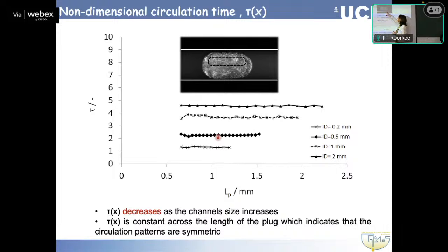and because we are at low velocities, the Hagen-Poiseuille equation in circular channels is good. In non-circular channels, there would be the equivalent one, but it's basically pressure drop correlations for laminar flow. In this part here is where the bigger debate comes in, and people say that we have to have a frictional part and a part that takes into account the fact that we have a circular bubble, the Laplace, we have to take into account the interfacial forces.